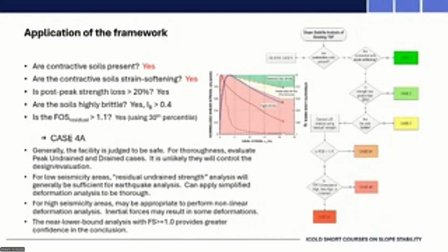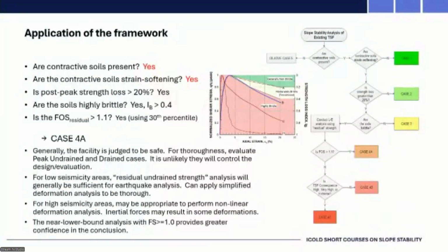If it was in a low seismicity area, we probably wouldn't worry about anything else. In a high seismicity area, we would still need to look at deformations, because even though static liquefaction isn't a concern, you could have enough deformation in your seismic loading to cause some concern, depending on how much freeboard you'd have.